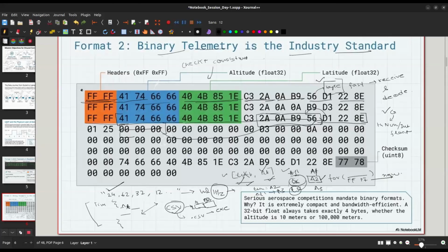This is one of the simplest examples that I could explain, and it is one of the most important scenarios to consider before you actually build a GCS. If you have a packet with FF, then temperature and then altitude, you say that whenever you receive this FF, then start decoding temperature and altitude. If you did not receive the FF, you are not going to decode the temperature and altitude values.